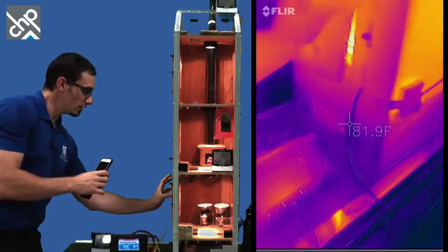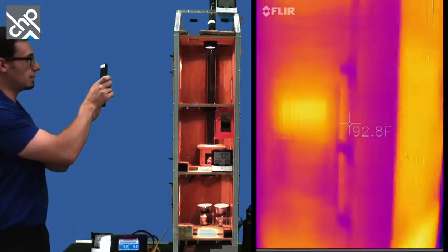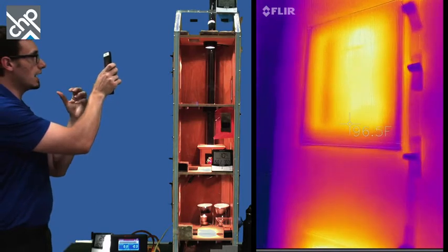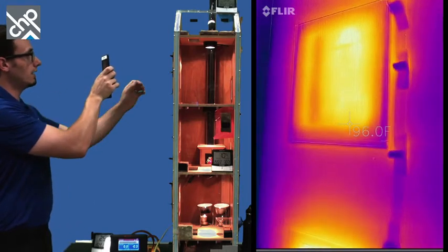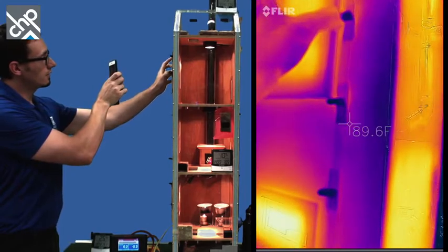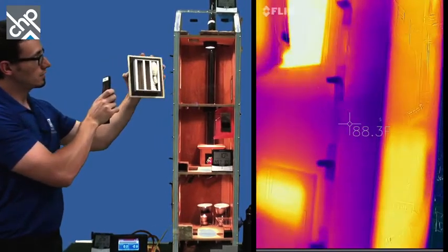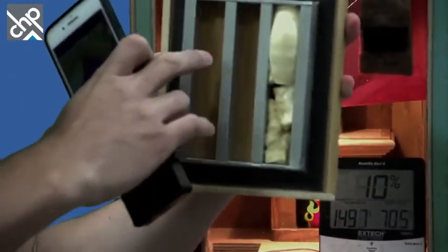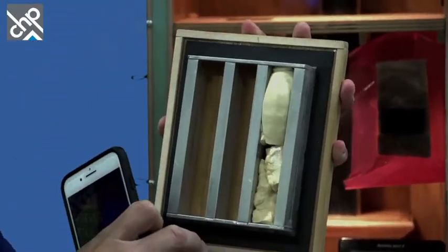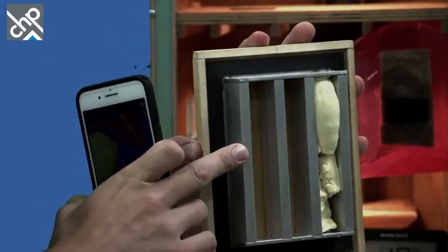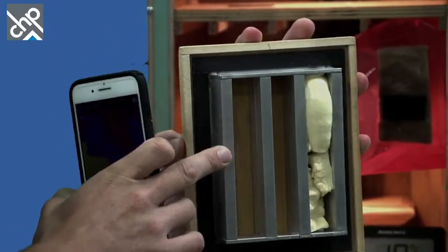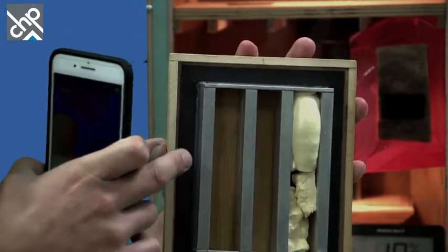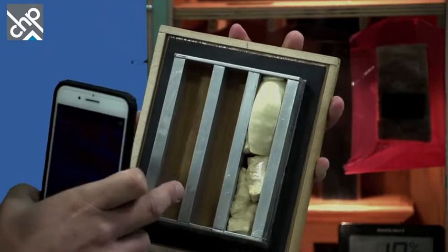and pull out the other wall section I saw up top, another thermal shot here. This one seems like it's a bit hotter, kind of all the way around. And the reason for that, pop this off, take a look here in the frame: we're actually devoid of insulation here. This is a metal frame. That metal, as compared to wood, is going to conduct heat more readily.